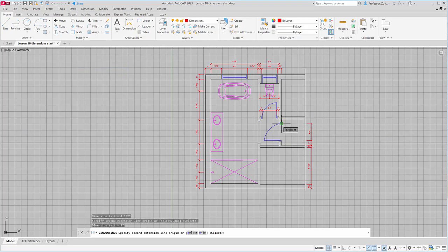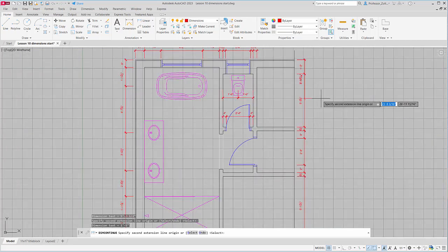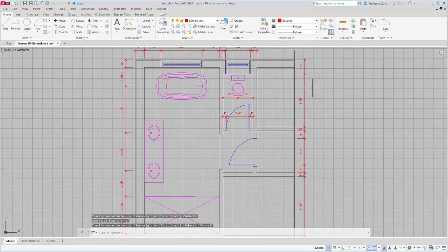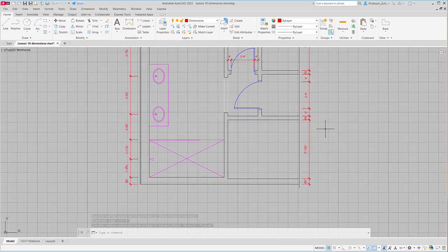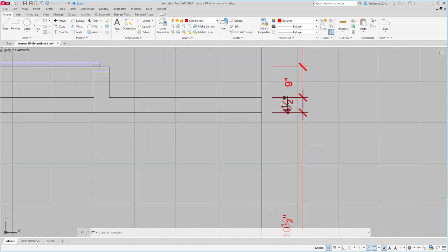Now remember, with doors, you do the inside casings. With windows, you do the outside casings. And it looks like this one's included and that. And now I can zoom out and verify. Just press escape once you finish your dimension string. Verify all those values. Now the other thing we can do here, because sometimes there's crowding, and you can see how the 4.5 may be interfering with these dimension lines.